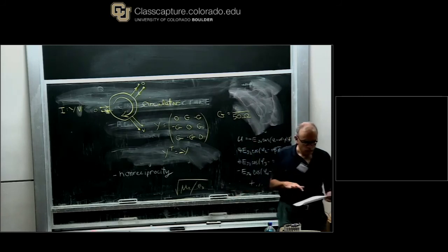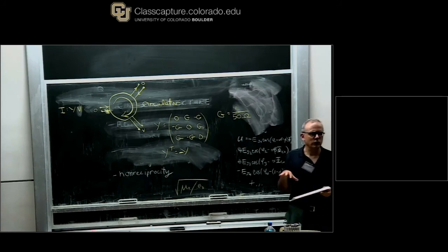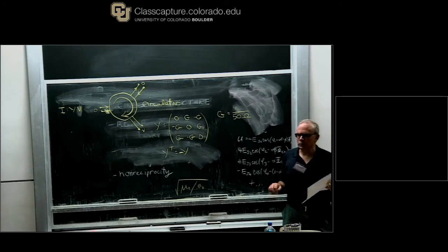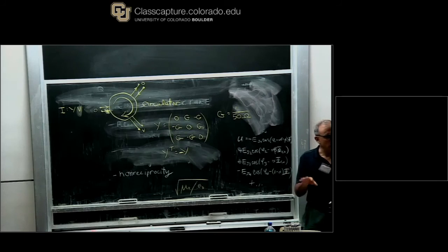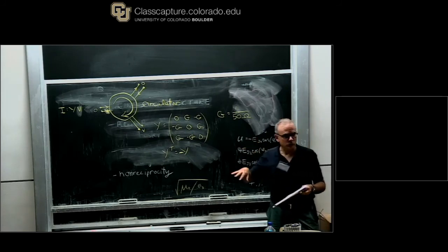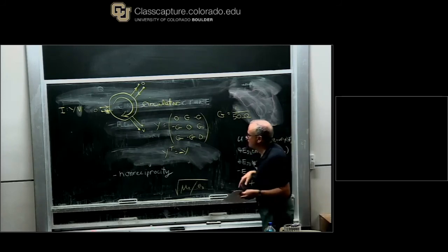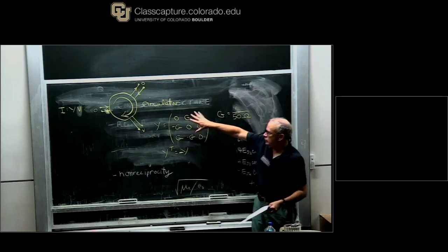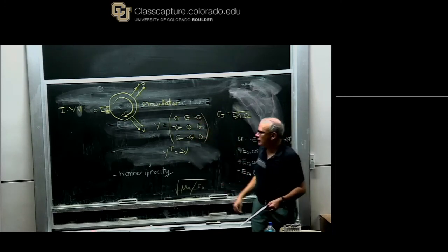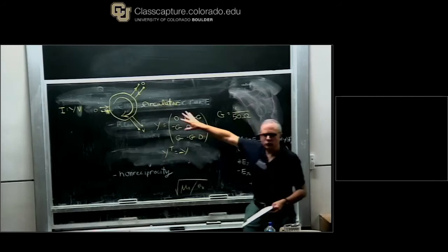Now there's some sort of rough correspondence between the dichotomy reciprocal, non-reciprocal, and time reversal invariant, not time reversal invariant, but that's only an incomplete correspondence. It's a correct correspondence in the case of lossless circuits. But reciprocity or non-reciprocity is a good concept also for lossy circuits. So one should be warned not to associate the two too closely. Anyway, this shows that there is something in the world that can't be represented by the toolkit that I've been describing, including a device of considerable interest.